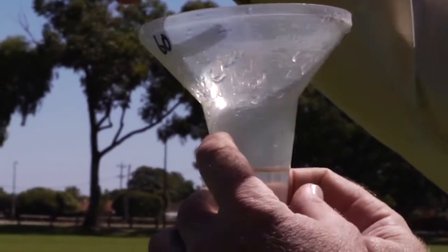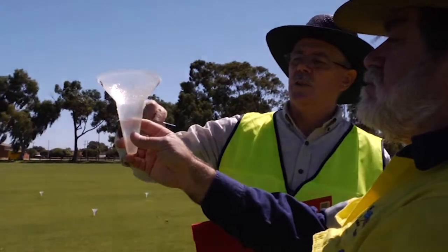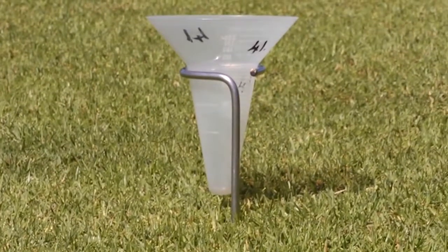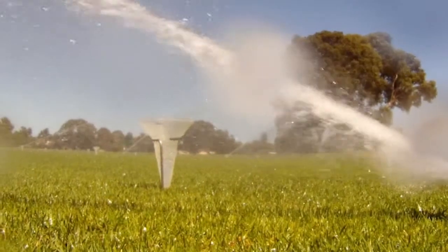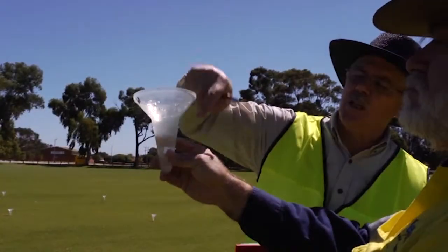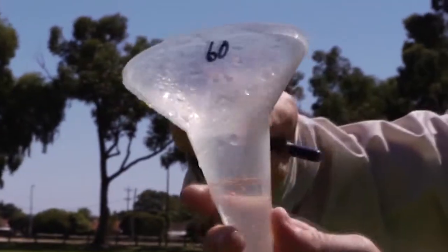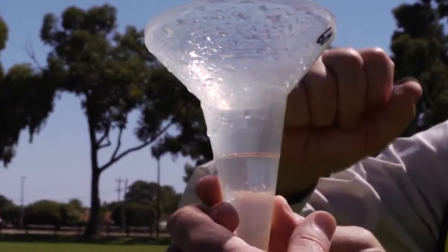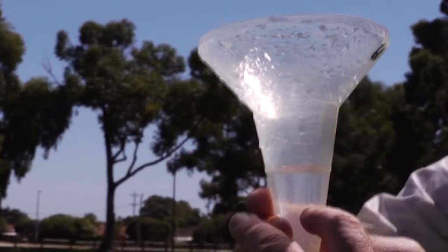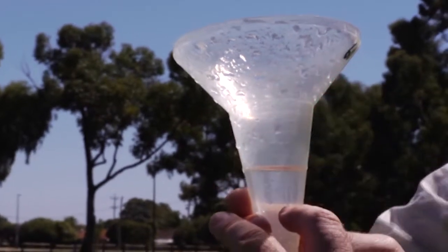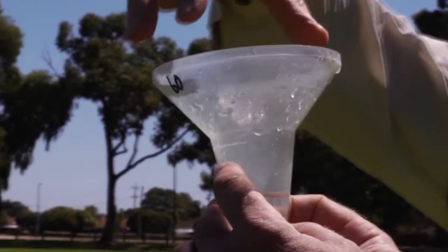These cups are specially designed for the purpose of catch cups in this application. They're calibrated and they've got a tapered holding receptacle at the bottom. So you get a large catch area, about 100 mil, and that's collected in this tapered section. One side is calibrated in millilitres and the other is in millimetres. So if you want to do a quick test for what the application rate is, you've got millimetres already on there. So they're specially designed for this thing.